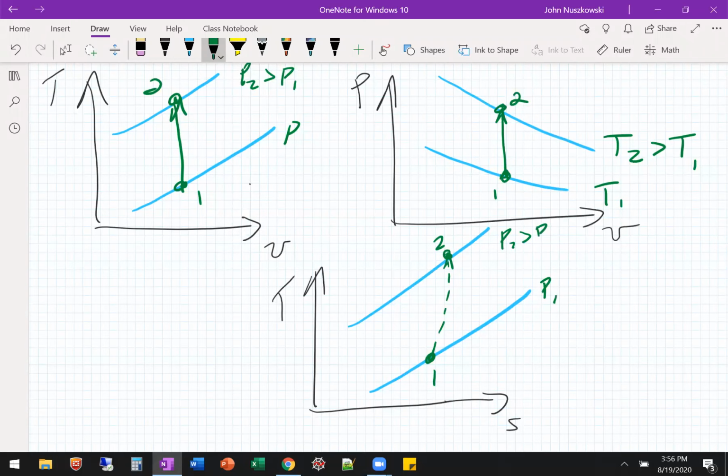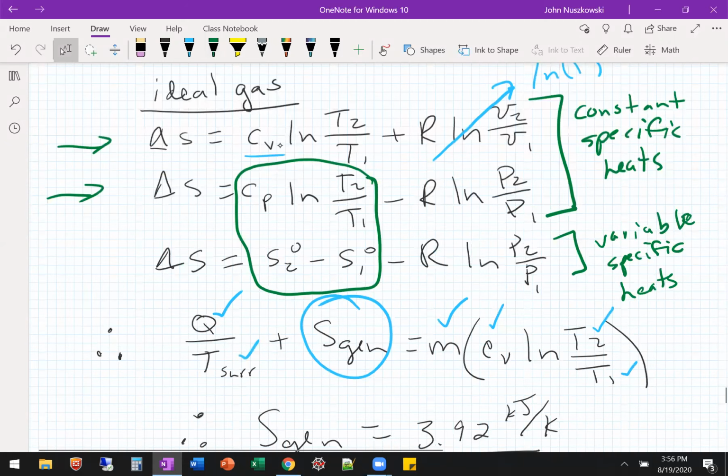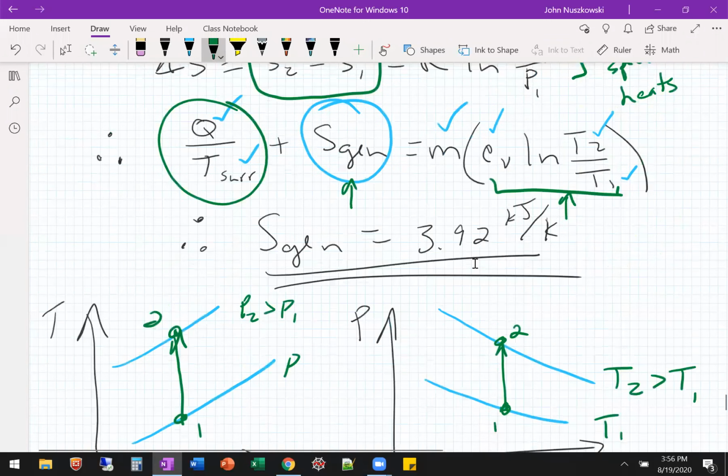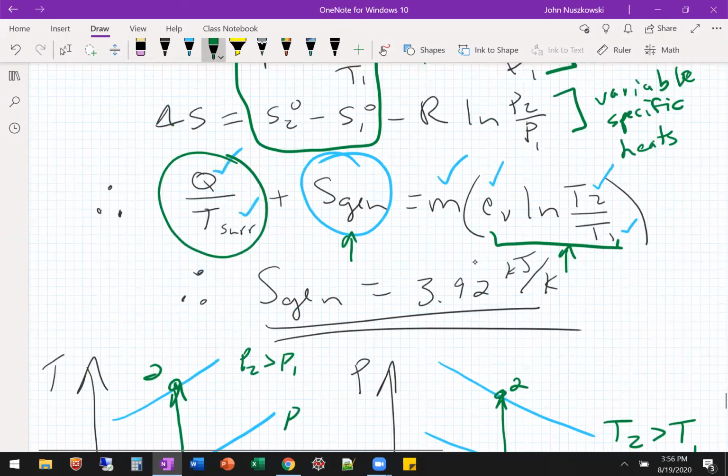And we can check this right here. So all we're plotting is this. That's delta S, right? SGen isn't always equal to delta S because you got this heat transfer. When there's heat transfer there, you could have a negative delta S and the heat transfer takes up the difference that still creates an SGen that's positive, okay? SGen is a different term than delta S, okay? So I know students get that one confused, okay? Sometimes they are related, right? If it was adiabatic, this Q over T goes away and SGen gets related to the delta S.